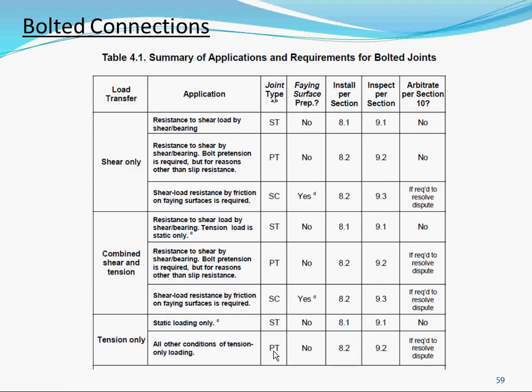However, we don't want to have the framers need a tool to pre-tension it. So we test it as snug tight. If somebody points out, well, your load is tension only, and it's not static loading, you should be pre-tensioning, the thing is we test it to be snug tight. And that's one condition we put in the code. We tell you what some of the exceptions in the bolting requirement are. In 341, all bolts need to be pretensioned, regardless. So for us, we put in that it be snug tight.